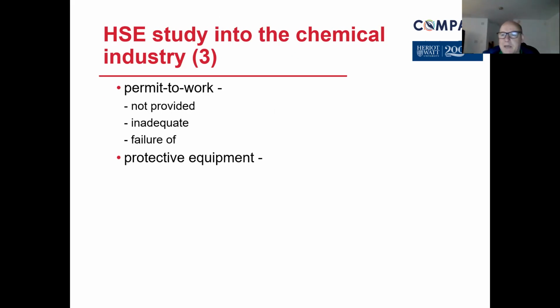However, from a safety perspective, it meant that equipment was isolated properly, it was purged if it needed to be, and there was a handover: the responsible person can hand it over to a competent person, a maintenance engineer, a contractor, and they then become personally responsible. And when they hand it back, the responsible person asks, what safety protocols have you followed to bring it back to a safe state, and so on. So it really did formalise an organised way of doing safe systems.